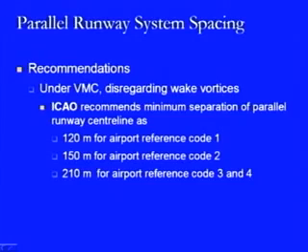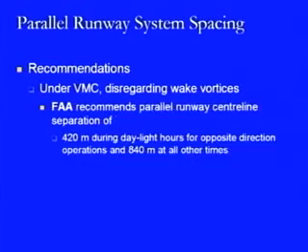Here the ICAO recommendations say that the minimum separation of parallel runway center line should be 120 meters for airport reference code 1, 150 meters for airport reference code 2 and 210 meters for airport reference code 3 and 4.